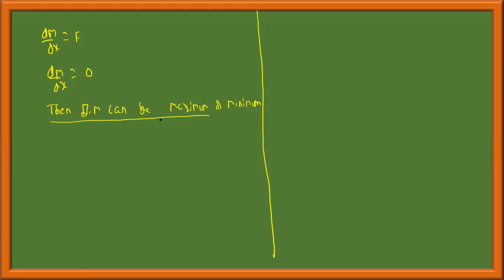While solving the problem, for example, this is the bending moment diagram. At this point, when you draw a tangent, the slope is zero. So the shear force is zero, and the bending moment is maximum or minimum. The other way to say it: when shear force is zero, bending moment is maximum. For example, when you plot a shear force diagram for A, B, C, assume that the shear force will be getting like this.